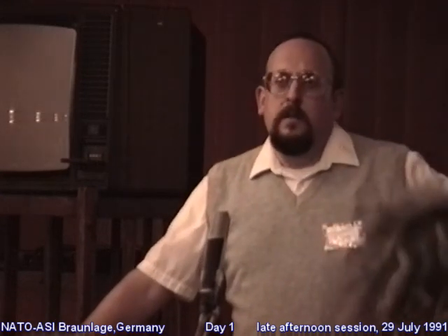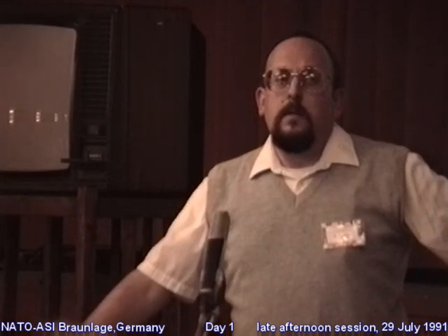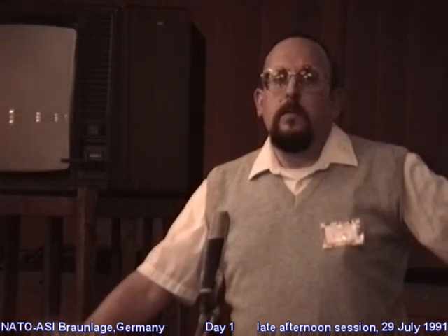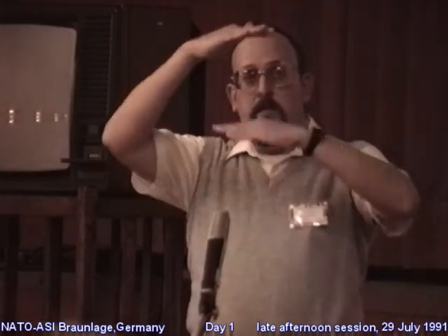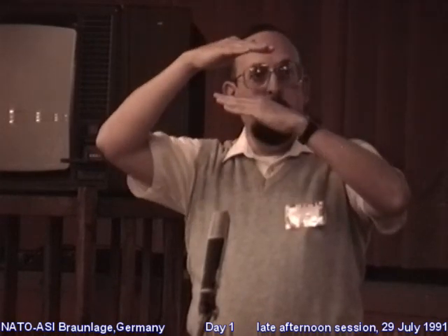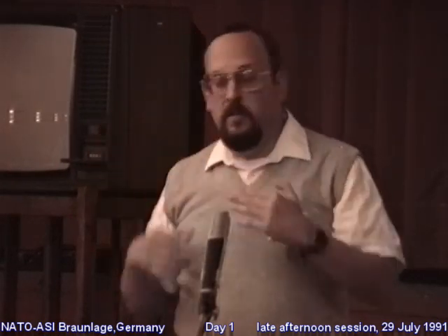Right. However, the range you quoted, is that instantaneous forces over the mean load, or is that averaged over some time? We essentially took several traces of reversal cycles after the system had reached steady state, and then came in with a caliper and just measured the maximum and the minimum.